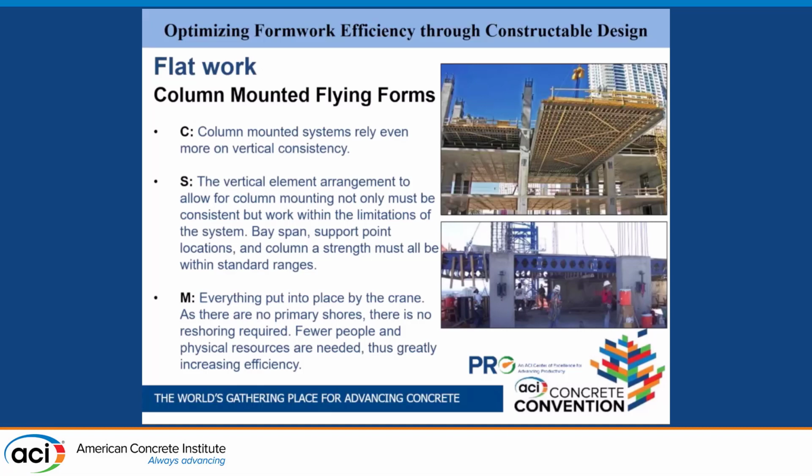So the bay widths, you're going to have to look at and find out what the sizing on those should need to be. The columns themselves, you'll need to make sure they're of a proper size so that you can actually anchor the panels off to them. We've seen some with very, very small columns, and you get loading on those and the column starts to move. So now you have to start bracing the column and dealing with that. Whereas if you go, all right, let's change the design a little bit, let's beef up the column, now we can have this thing fit in here, and we don't have to do all these other solutions. So you're increasing productivity through that small design change, just by talking to your former contractor.